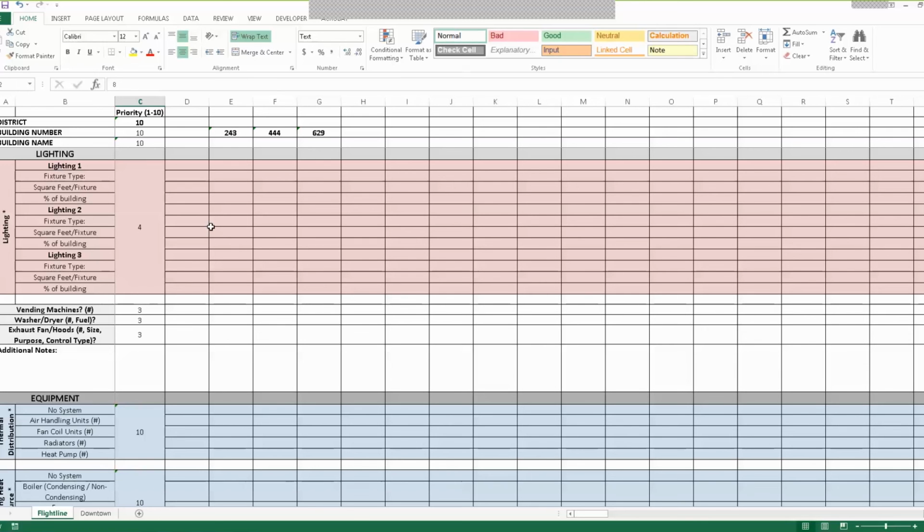What I think is the biggest thing that we find in many cases, and if you happen to do these with lumen meters, you'll find that many spaces are overlit, and that's where you can get big savings. When you're consistently finding buildings that are overlit, you might want to get a sampling of the lighting wattage level per square foot, and like I said, do that simple calculation to get it.